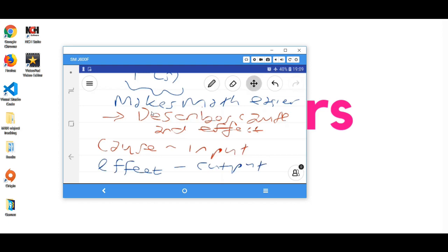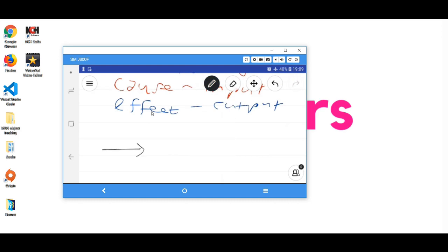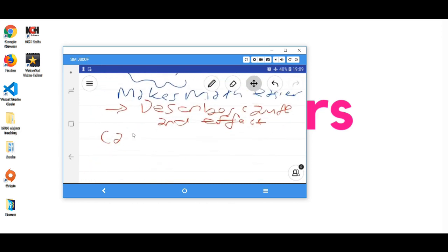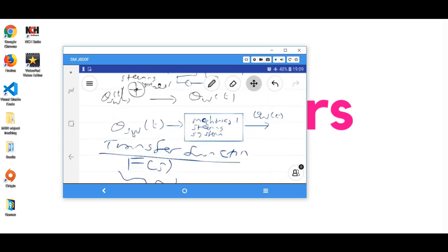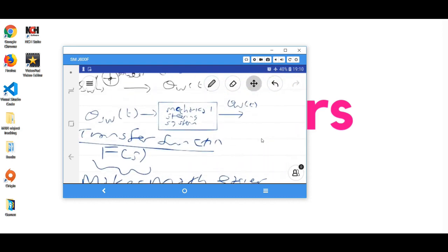So what this looks like, if we go back to our steering wheel controller, is this. Originally we had our controller here, with our input in terms of time. This is our input, and this is our output. The input is the steering angle, and the output is the angle of the wheel, right? And remember that there's no feedback here. This is a manual control system, and that's why it's open loop.